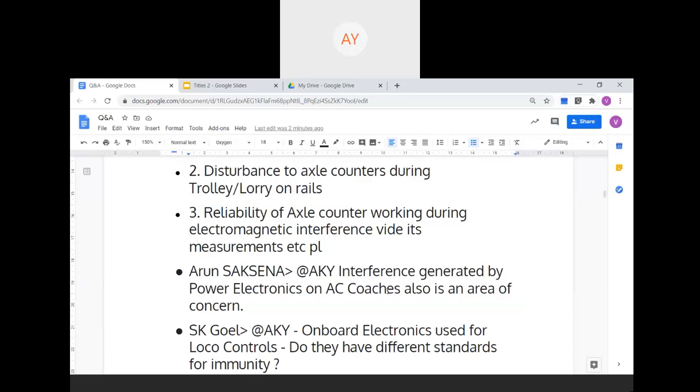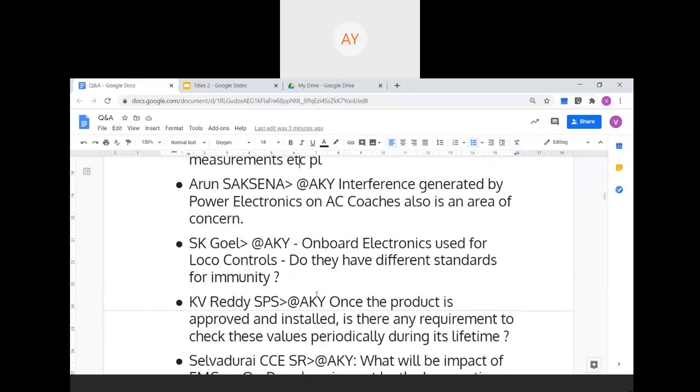but it also relates to the operation being planned. Why should we have a sensor placed at a place where shunting operation will necessitate a train wheel to stand on the sensor? You place it further away. It all depends on the operational planning as well. It is not as simple as placing a sensor and then detecting each and everything, whether you come halfway or go full way. So the technology has its limitations.